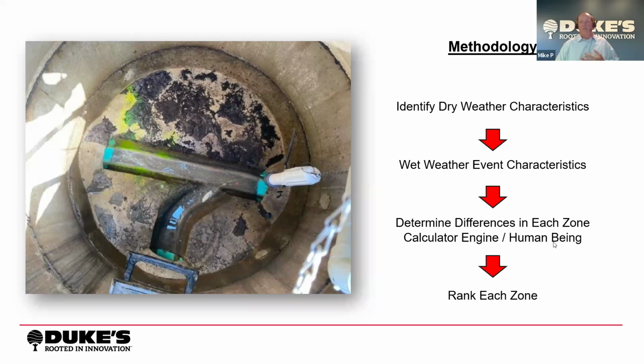Now, if there are any engineers on the call or people that have been around flow studies, it's common to get the question, what do we do about velocity? As we're giving out volumetric numbers. So we do take a velocity measurement when we install the equipment originally. And then we do a balance of the flows under dry weather and a balance under wet weather. And with all the calculations and experience, we feel very confident about the results.